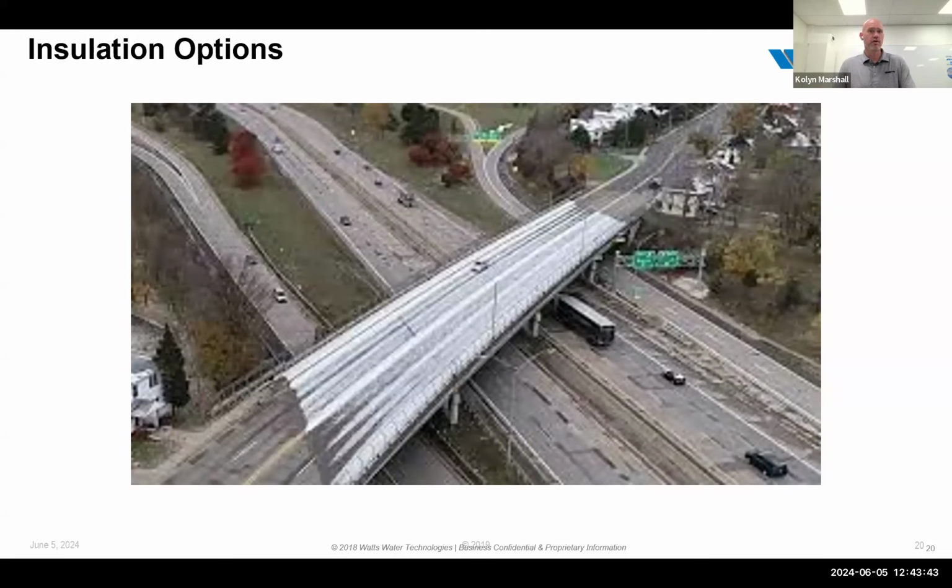So we overcome that maybe with an early start, or you can overcome that by just letting it run longer. The longer it runs, the more BTUs it pulls. Absolutely true. Insulate that slab, and you decouple the slab from the earth below. It will respond faster. Here's the caveat. The quicker a snowmelt system comes up to temperature, the quicker it's going to cool when the system shuts off.